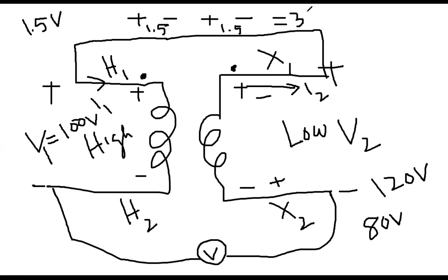It will be 3 volt, right? Like plus minus, plus minus. If you connect the battery that way, it will give you 3 volt. But if it is plus minus and then minus plus, then ultimately you will be getting 0 volt because it is opposing.